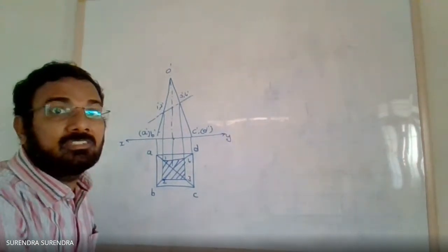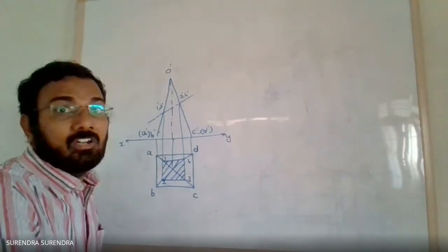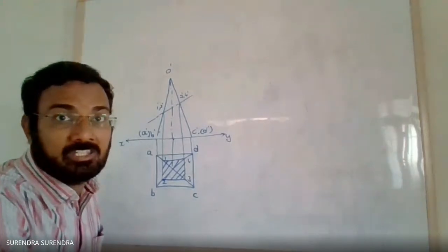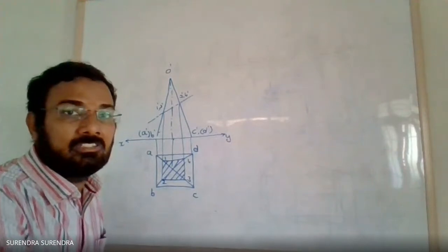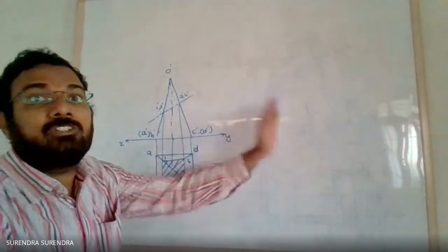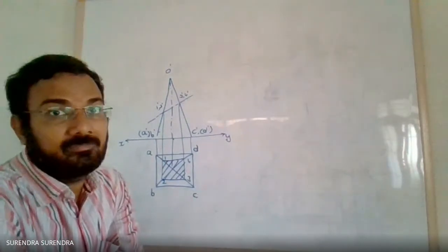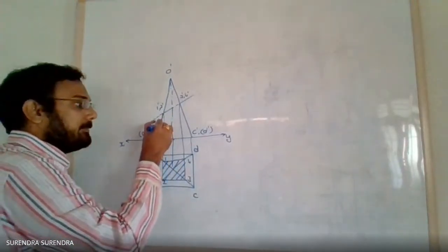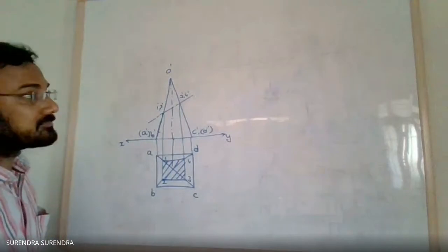So this is the shape of the projection of a pyramid when it is cut by a section plane inclined at 30 degrees to HP and bisecting the axis. Now, drawing the development of the lower portion of the pyramid. Remember, only highlight the base. Leave the upper part with a 2H pencil.